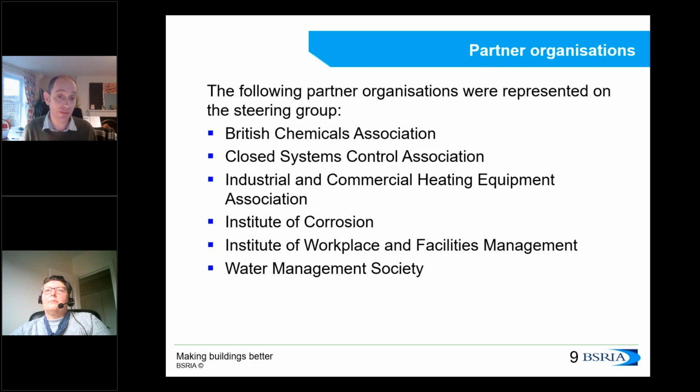If you are using water treatment chemicals, they also need to be compatible with metals on the system. I believe there is one particular type of plastic, and I can't remember which, that sometimes runs into issues when you also have copper in the system. I will try and provide you with some more information about that, Engin.